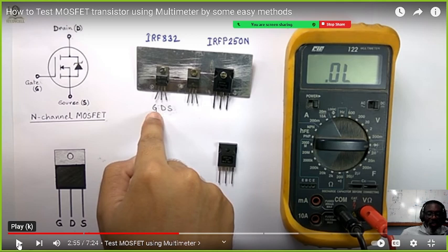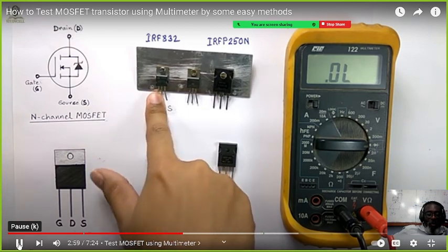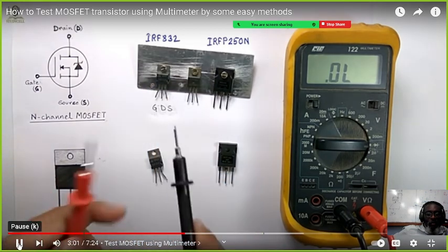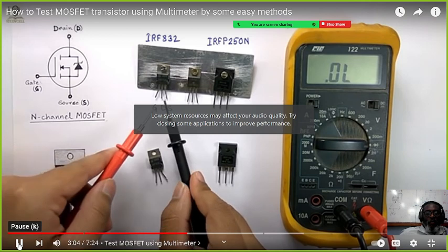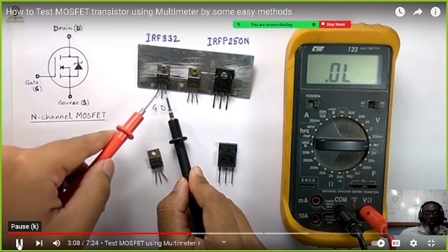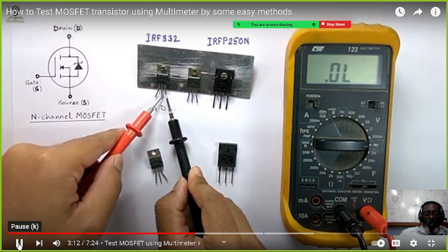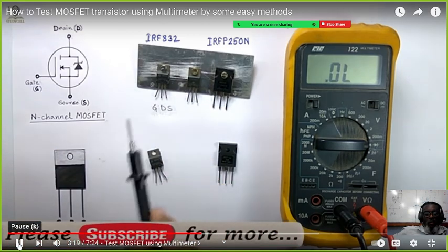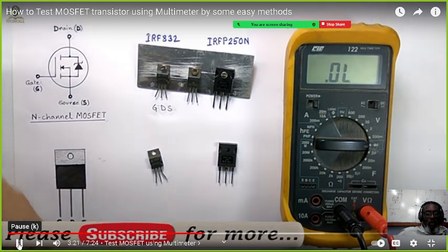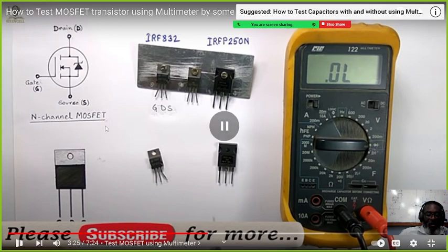All right. I discharge the terminals with my finger for a while, so I shall check it out again. Now again the MOSFET is in off state. You can confirm it by connecting the black lead with the source and red lead with the drain. I am getting nothing, no continuity, until I turn it on between these two terminals. Turn it on now. So the MOSFET is okay. Thus we have checked the MOSFET both in on state and off state, and it is okay.